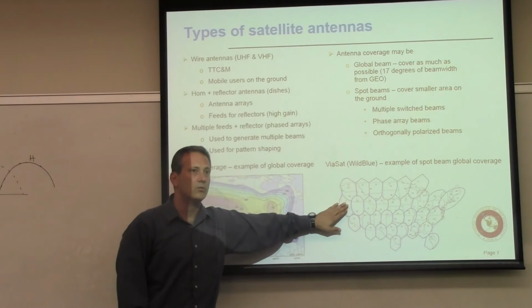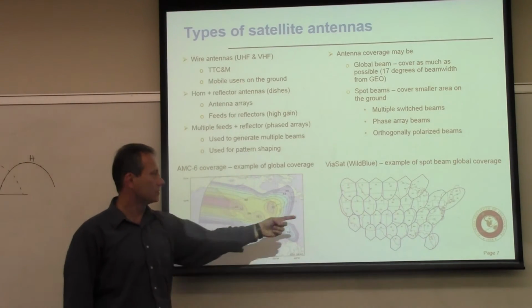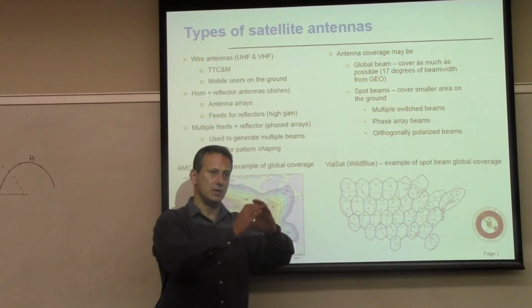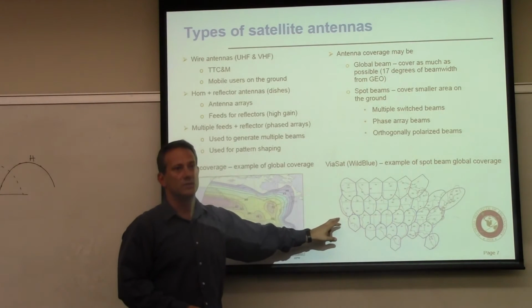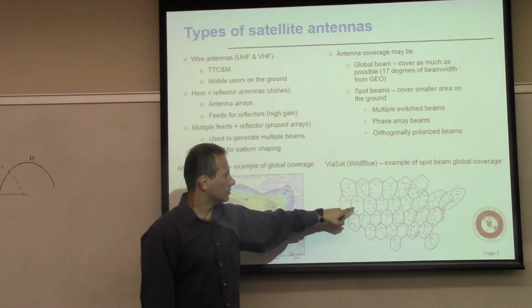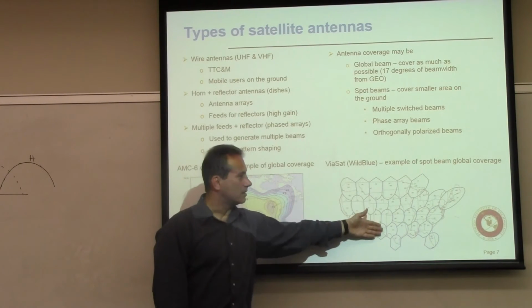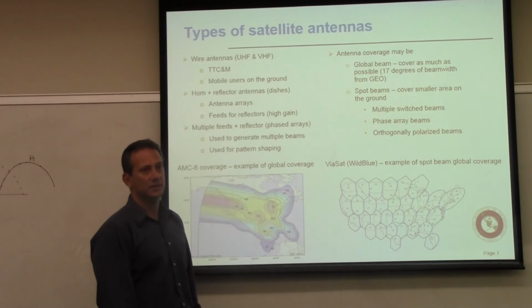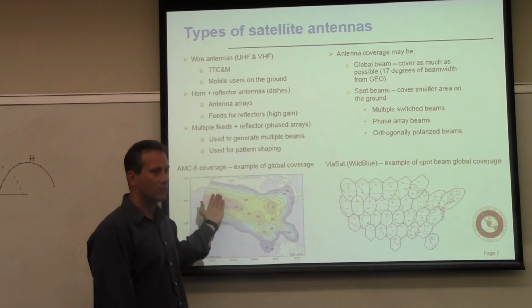These days we're kind of moving towards this concept for two reasons, because you can provide more reliable coverage because you're now covering a smaller area. You can focus the energy only there. And then the second one is you can reuse the frequencies. So you can now use the same frequency here and here twice, or many times throughout this area, and get a higher capacity than in this case here, because you have one antenna.